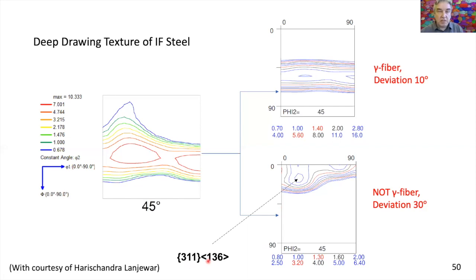So this brings to the conclusion that this component is very widespread in BCC low carbon steel. Even if it's not a majority component, and only surfaces under very specific conditions, it is present in daily common deep drawing steels, and we now even have a serious indication that this component is responsible for some property aspects of the material.